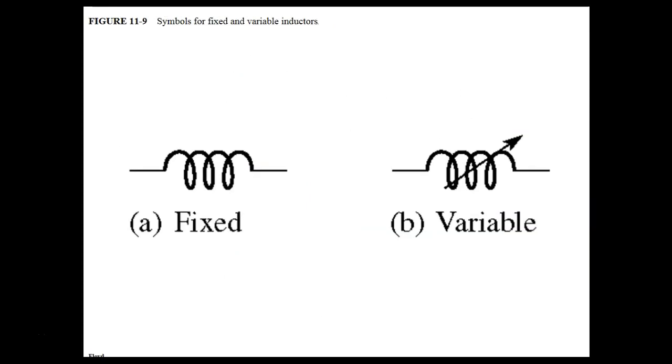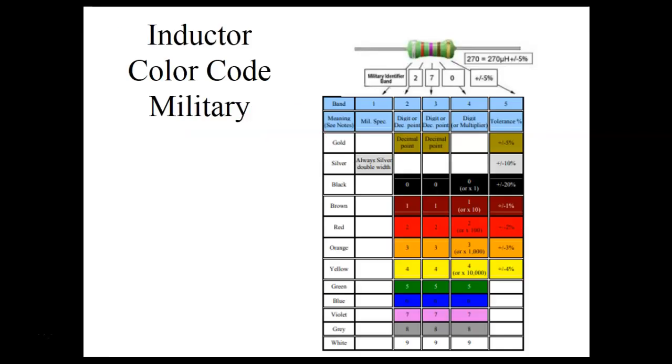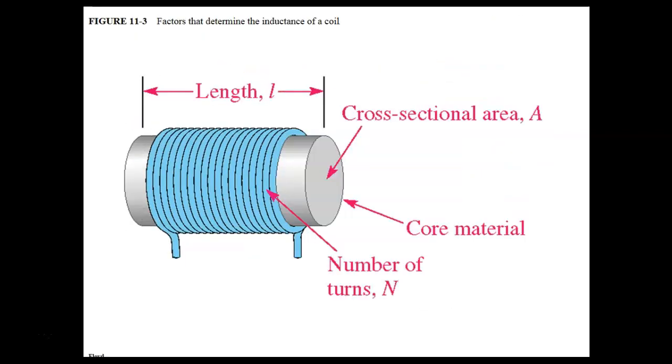So these are symbols. I have some, let me find my thing over here. So what would I do if I don't have an adjustable capacitor? What would I have to change? I mean, an adjustable inductor. What would I have to change? The inductor would be core material. Could change the core. Could change the size of the core.